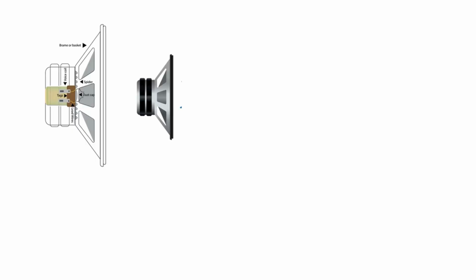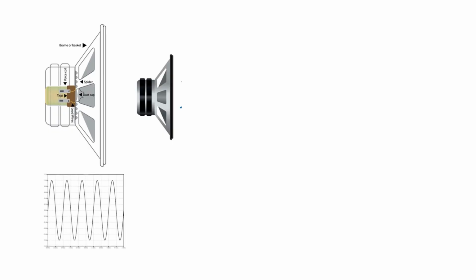We now need to look at a property of an alternating wave called wavelength. Wavelength applies only when the vibrations resulting from an alternating wave begin to travel through a medium, like air or a wire conductor. Sound waves are a good way to learn about wavelength as they are easy to visualize. This is a loudspeaker in an audio system. It turns an alternating electrical current into mechanical vibrations that we can hear. We will connect an amplifier, generating an alternating audio waveform to the loudspeaker with a frequency of 1000 Hertz.